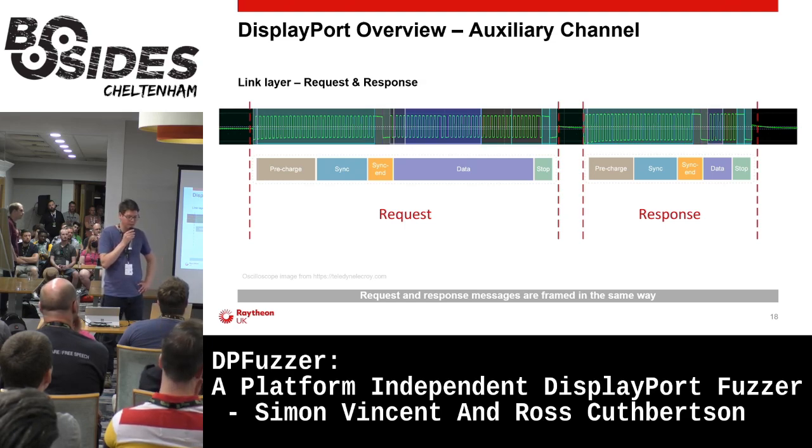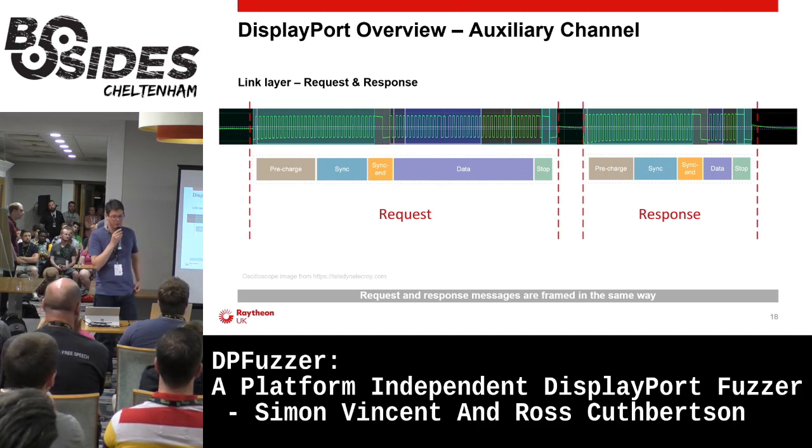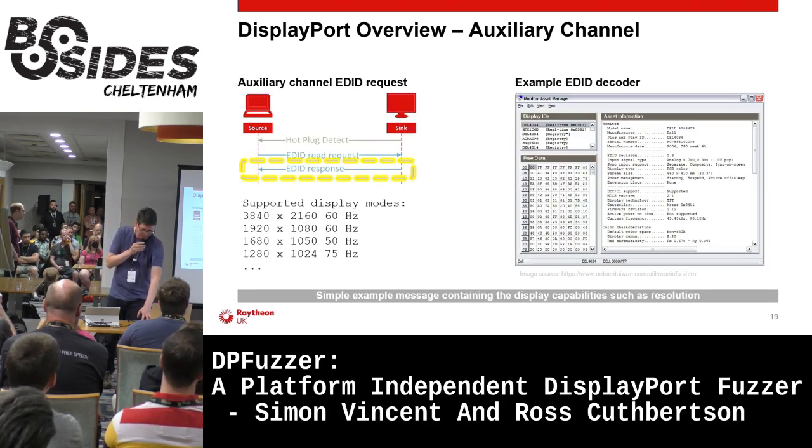And as you can see, there's a short period of time in between the request and response. There's a maximum of 300 microseconds, but typically we want to be much shorter than that to keep timings down. And this is a constraint that we need to deal with when designing our system.